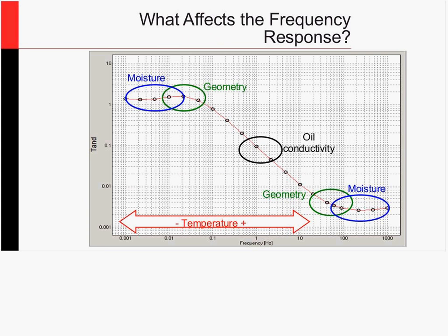On this next slide, this is giving an indication that power factor is going to be influenced differently depending on what frequency I'm doing a measurement at, because I've got two things contributing. I've got conductivity and I've got polarization processes. Depending on which frequency you're at is going to dictate which of those two is likely to be dominating the measurement. So this is just showing you, at any given part along the response, which force is really dominating the measurement.